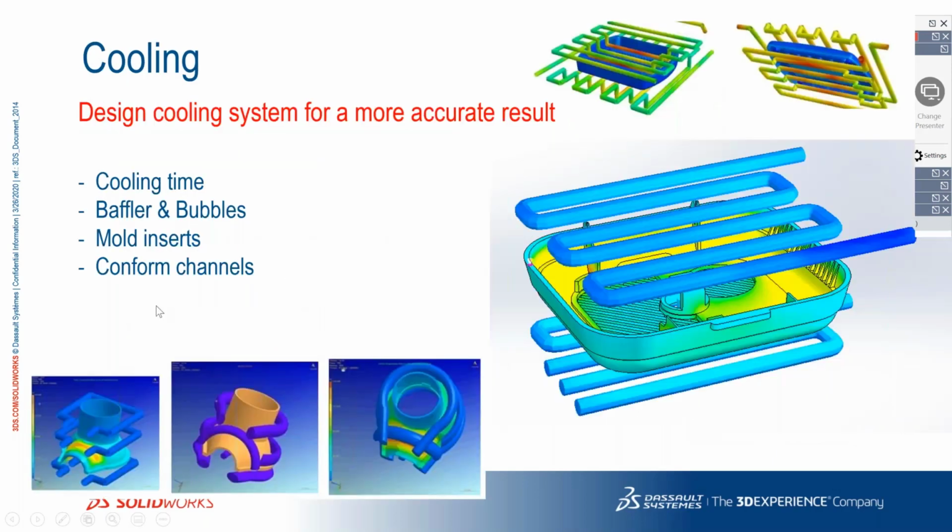So design cooling system for a more accurate result, where you can have the cooling time analysis, baffles and bubblers. You can see the different cooling layouts given inside this example, the different channels, and the adequate cooling for mold inserts and conforming channels, where the inlet and outlets are specified, how the coolant flows inside, and where it is going to touch the peak temperature, and what is the level of cooling to be given to make sure that adequate cooling is given inside the mold,